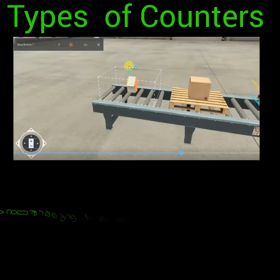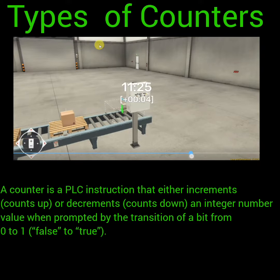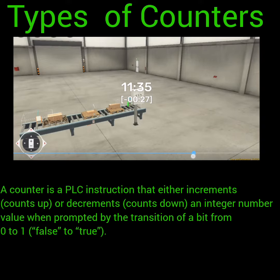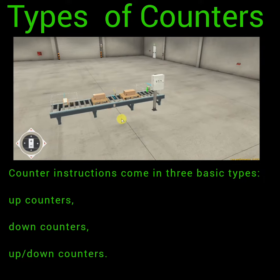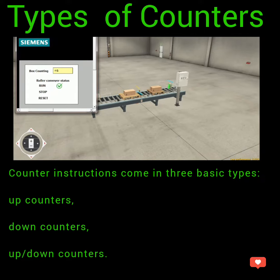A counter is a PLC instruction that either increments, counts up, or decrements, counts down, an integer number value when prompted by the transition of a bit from 0 to 1, false to true. Counter instructions come in three basic types: up counters, down counters, up/down counters.